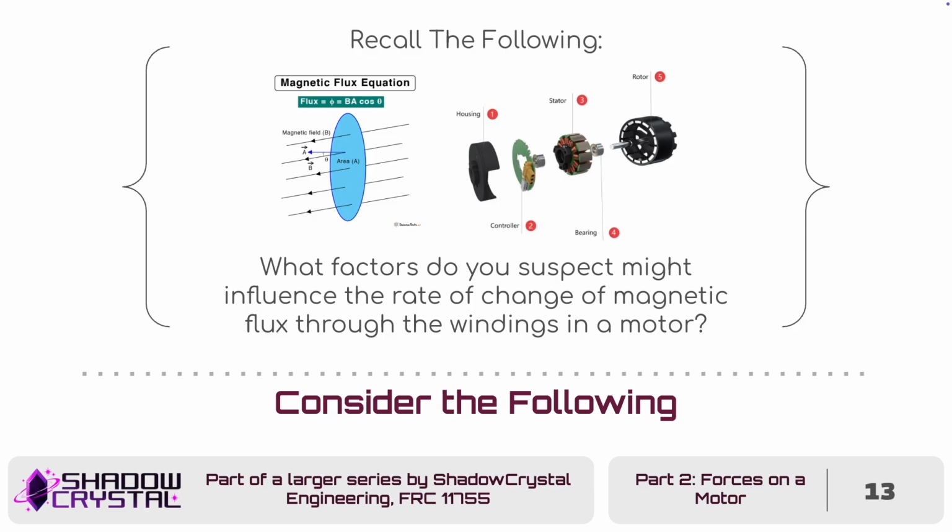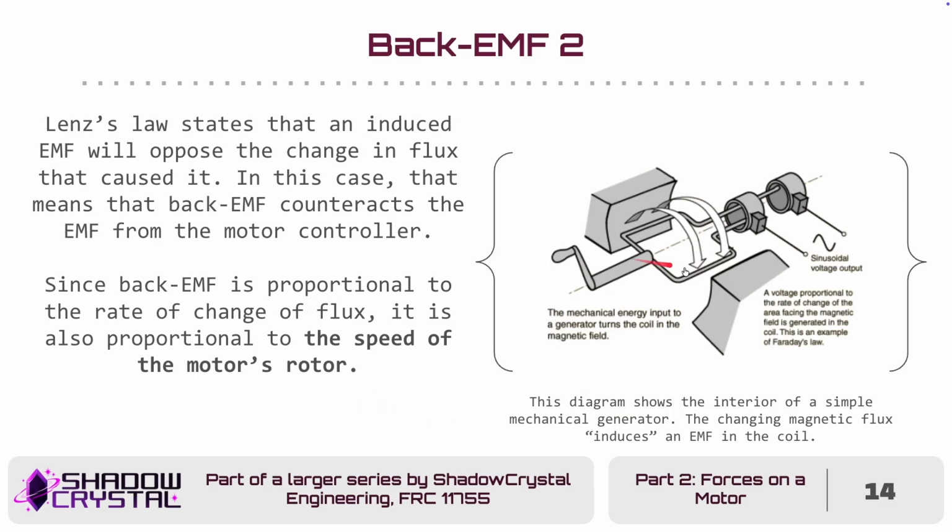when you turn this, so I'm just going to go back to this slide. When you turn this crank faster, this winding rotates more rapidly. And so you're going to get this change between no flux and maximum flux happening much more quickly. So yes, speed is proportional to the rate of change of flux, meaning that back EMF is proportional to speed.